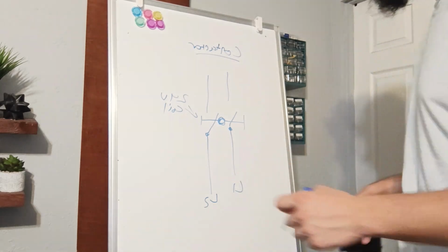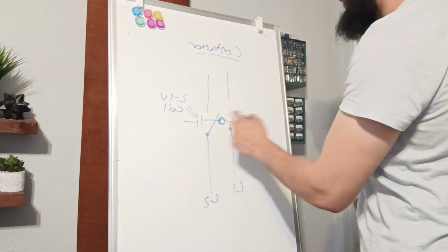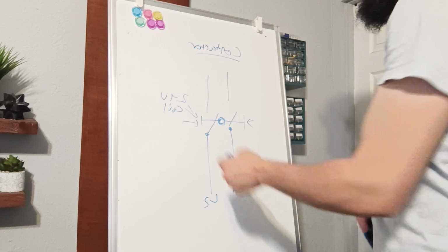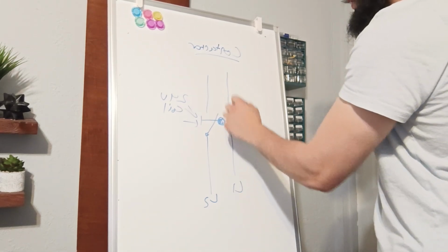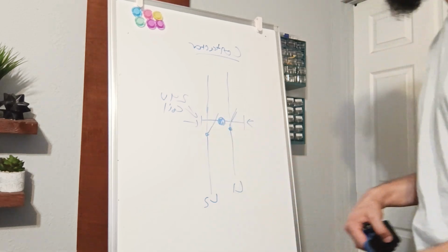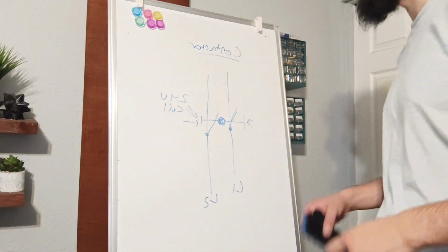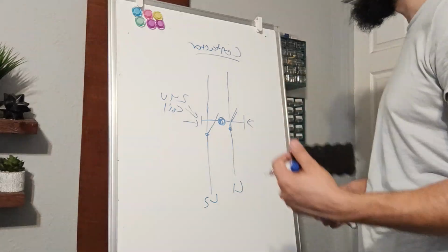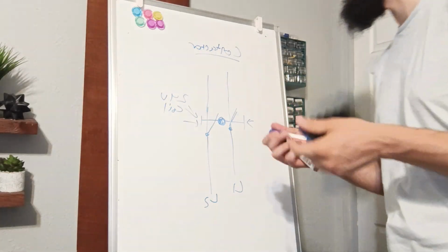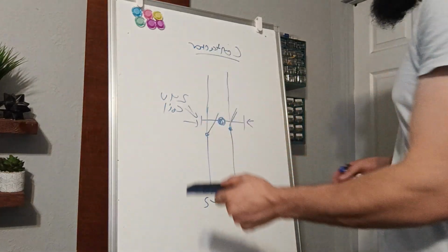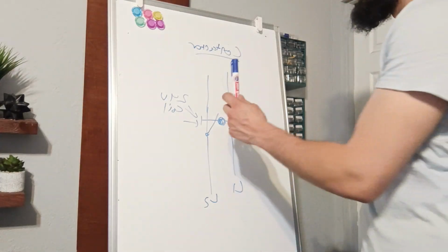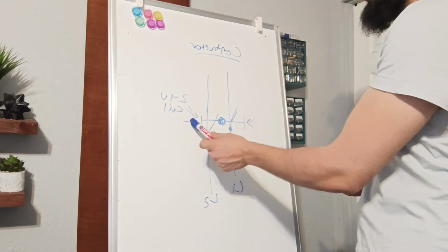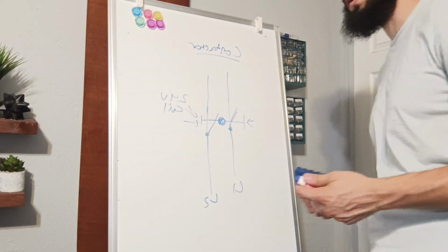So when you get 24 volts on this side and this side, you complete a circuit that magnetizes this coil. It sucks these contacts in, so essentially it closes the circuit, sends the power up to the fan motor and the actual compressor. So essentially, to see if you have a bad contactor, what you would have to do is a voltage check across these two terminals, A1 and A2.